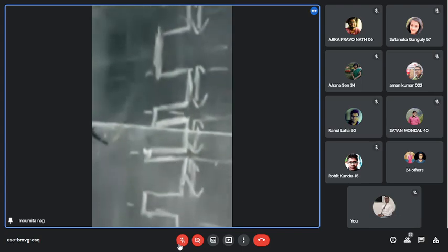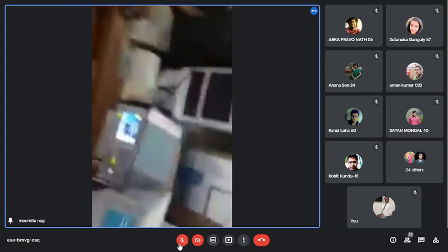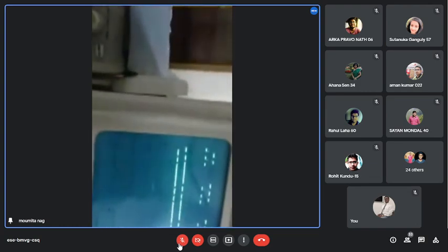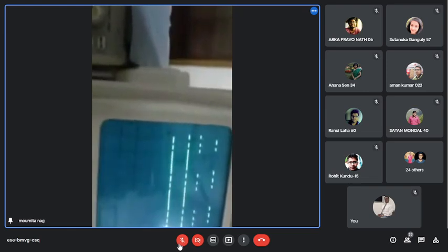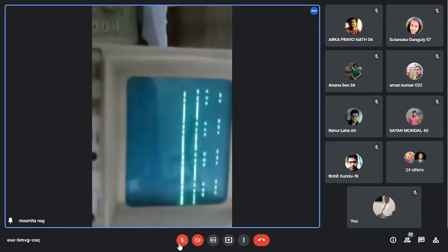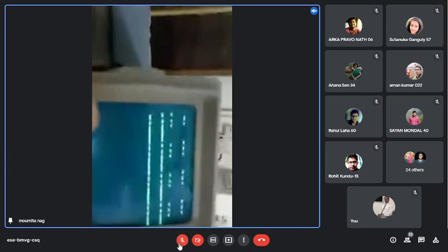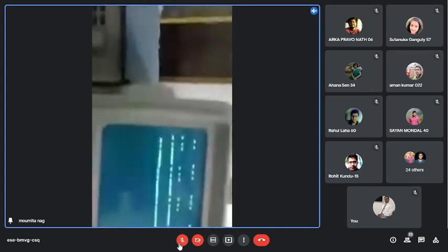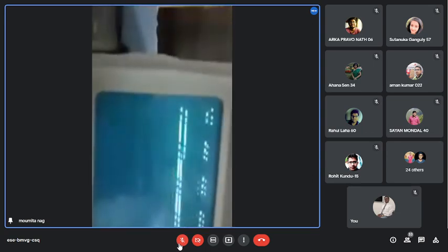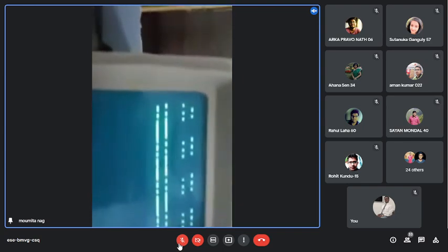বোঝা গেল? Yes, ma'am. এটা দেখলে কি তোমরা বুঝতে পারছো যে অফ পিরিয়ডে চেঞ্জটা হচ্ছে? বুঝতে পারছো? অ্যাকচুয়ালি সিআরওতে তোমার ওই পালসের যে স্ট্রেট লাইনটা দেখা যায় না, জাস্ট অন আর অফ এর হরাইজন্টাল লাইনগুলো দেখা যায়, ভার্টিক্যাল লাইনগুলো দেখা যায় না। কিন্তু ঠিক করে দেখলে বুঝতে পারবে যে যখন তোমার স্টেট চেঞ্জ হচ্ছে, অন থেকে অফ হচ্ছে, তখন PPM এর পালসগুলো জেনারেট হচ্ছে।